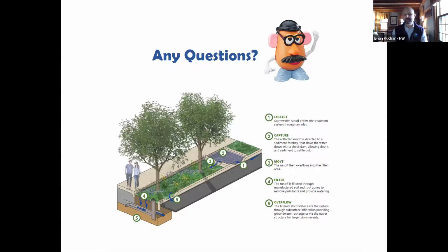Do you guys agree? Yeah, I would mirror what Brian said, that oftentimes in an urban setting, you're dealing with utilities. And while we do our best due diligence to locate those utilities with Dig Safe or otherwise, there's always that pipe, be it a private line or a street light line, that doesn't get located. And if you're out there, and again, I'm not knocking the proprietary tree filters, they certainly have their place and they are very effective. But you've got this big concrete box and you've got a utility line and you're reacting at a time when the street's open and you come across something they didn't expect. It's difficult to move forward with that if you have those constraints.